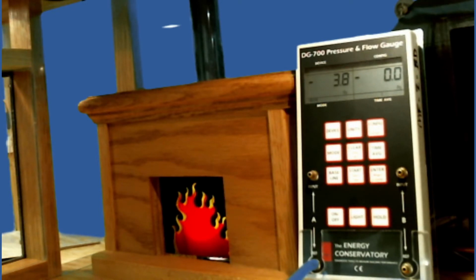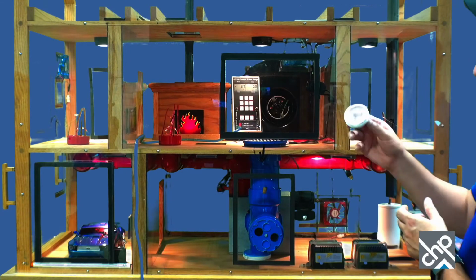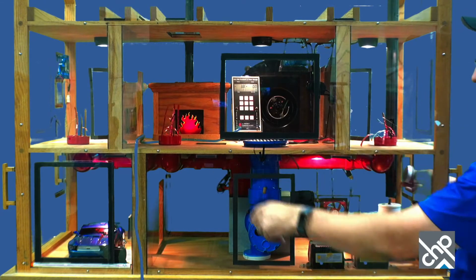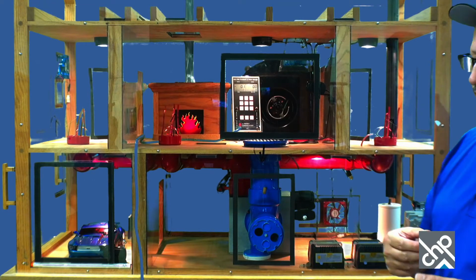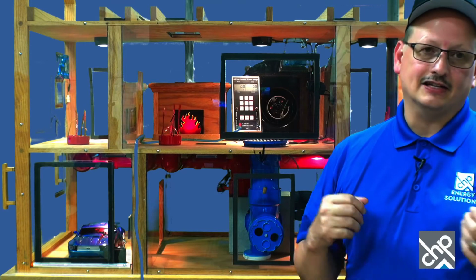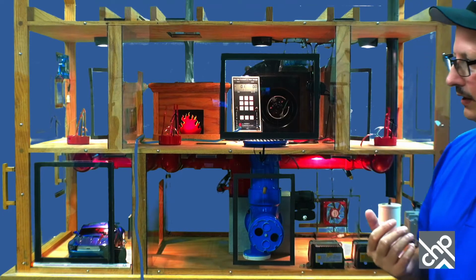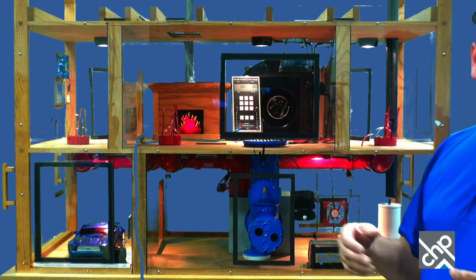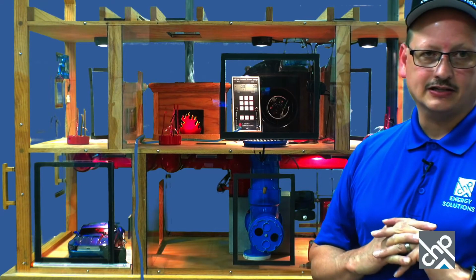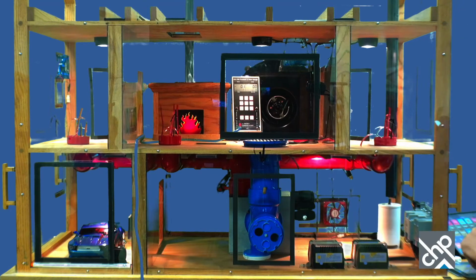And so I'm going to go back here on the outside. So I made the same leak that I made before. I also have one over in the garage. I could have done the same thing. As soon as I plug that up, pressure balances, smoke goes out the chimney. So you can kind of see how all those things get affected just from duct leakage, and all the indoor air quality, health and safety, comfort, and durability. If I've got negative pressure, we could have moisture issues, that kind of stuff, as well. So I'm going to shut this off.